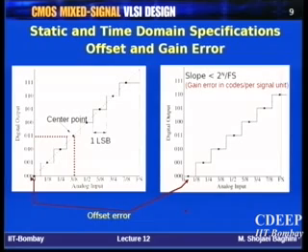So this leads to some sort of offset error in the characteristics of the ADC, and that is exactly the characteristic which is called offset error. What you observe is exactly like the analog case. If you have an analog output versus some analog input, if there is an offset, you will get a shift to the right or left, depending on the sign of the offset. If it is positive, you will go to the right. If it is negative, you will come to the left.